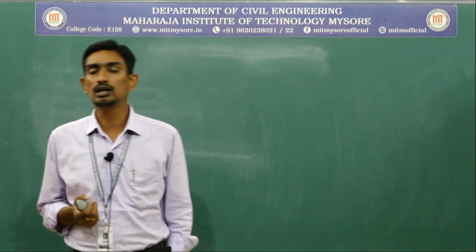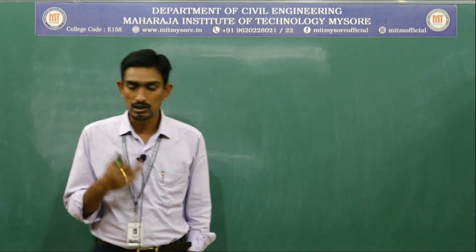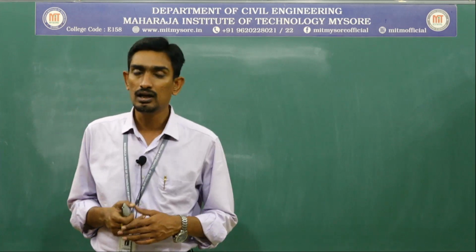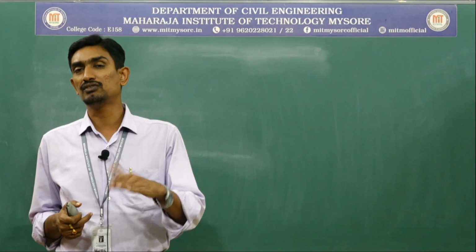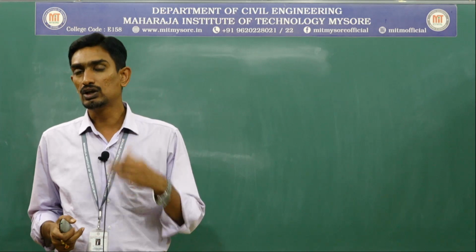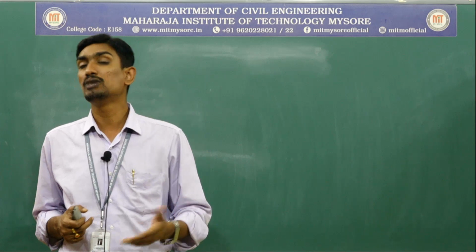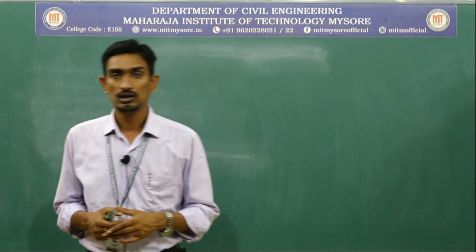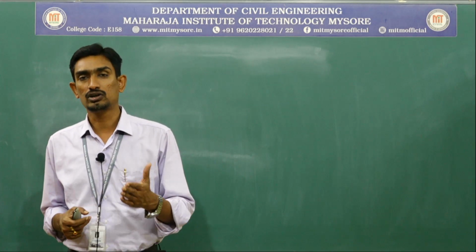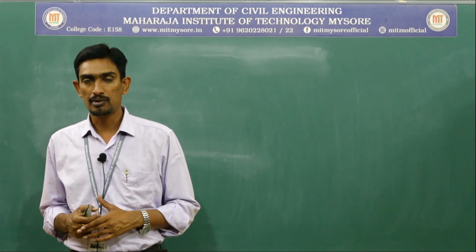So this is a completely go-green concept. In this we can make it even greener by replacing the cement with fly ash. Instead of using completely cement, we can go with cement plus fly ash. So there also we can minimize the cement content. Did you get my point? Or else you can go with a fly ash and lime combination. Did you get my point? Why?